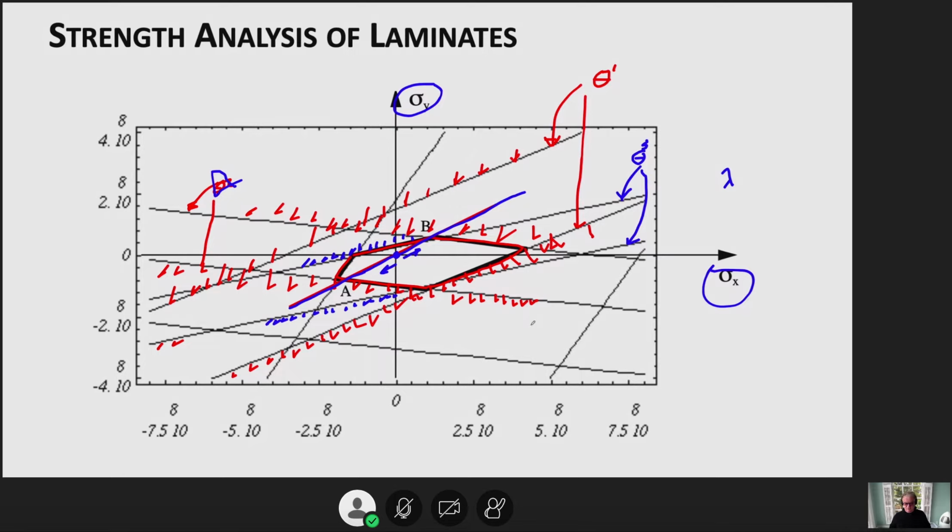All right. So we're going to actually now look at the tutorial, but we're not going to do the laminate showing this kind of diagrams. We're going to do first a single layer to see how the sigma x and sigma y envelope change, and how the different failure criteria. Well, actually, we're going to be mostly looking at the single layer, but how the different failure modes interact within the single layer compared to the fiber and matrix failures independently.